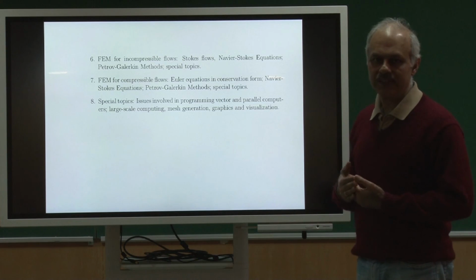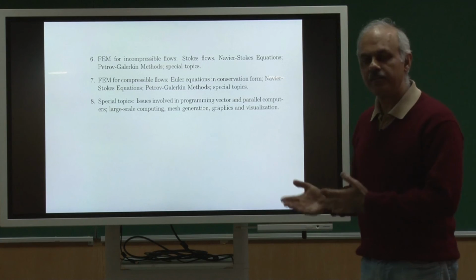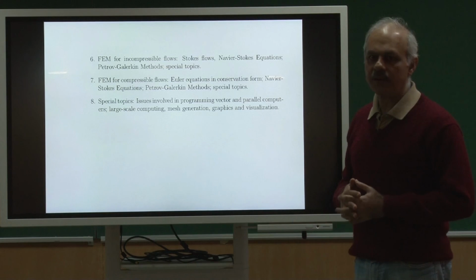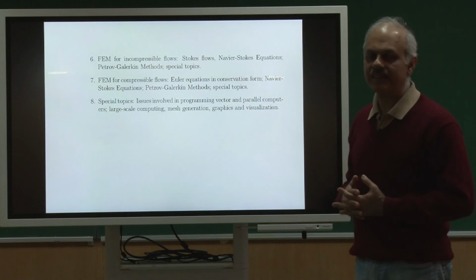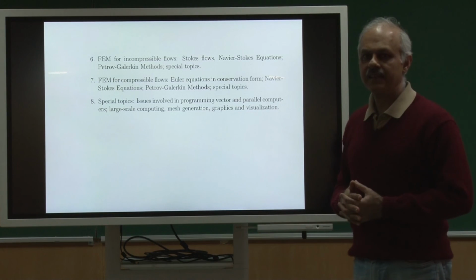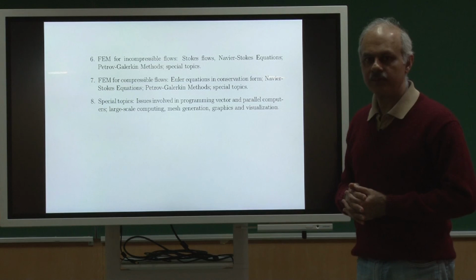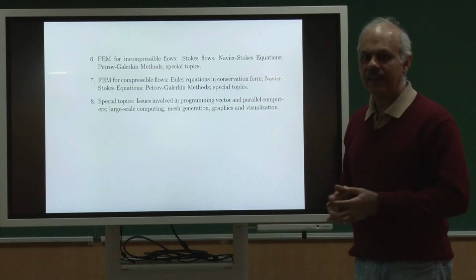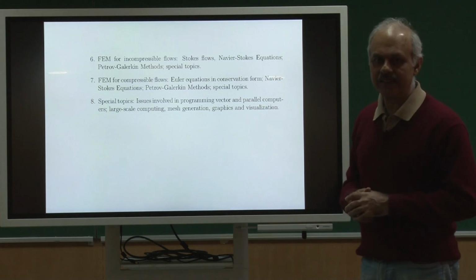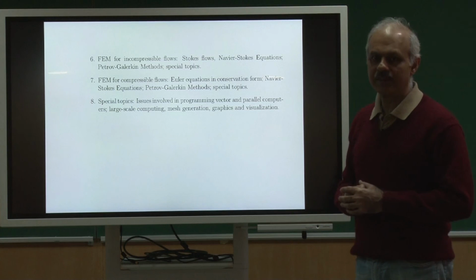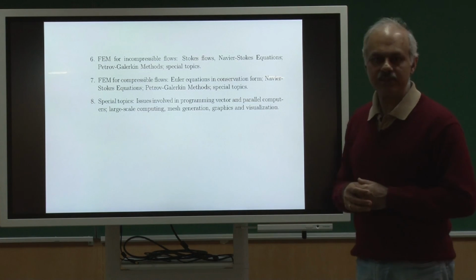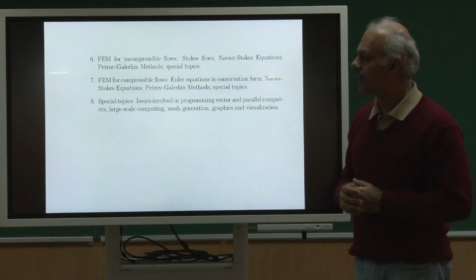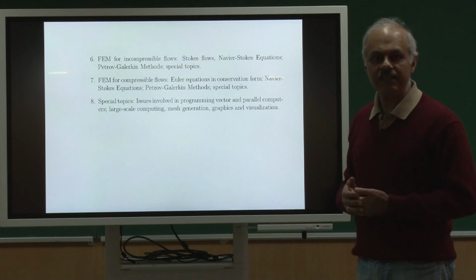So this kind of incompatibility between the order of the various transport terms in the equations also has implications for the order of representation that I can use numerically. If I am using, let us say, second order terms for velocity, and I try to use a second order approximation for pressure, you can see there could in principle be some problems because the order of derivative is different for the two. So then how do we deal with that?